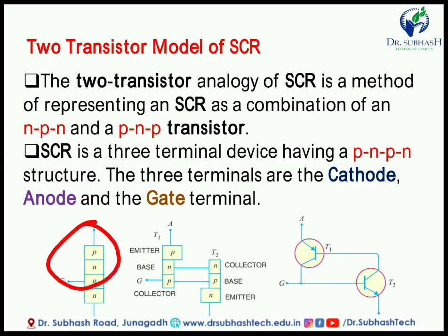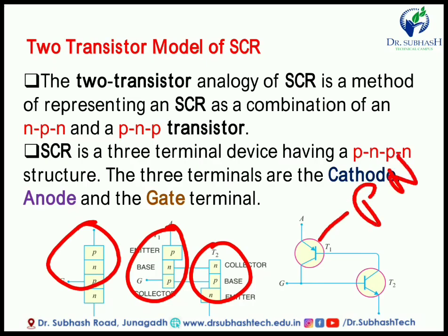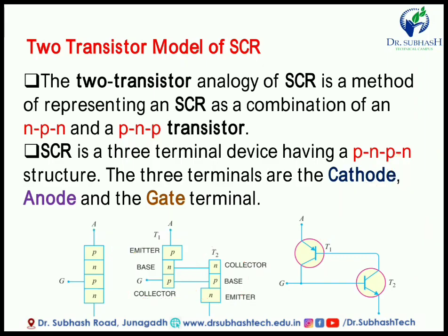Now in this tutorial we discuss T1 and T2, which means we use two transistors. T1 is a PNP transistor and T2 is an NPN transistor. There are a total of 2 transistors, and according to the conduction and blocking of these transistors, the current is different. In the symbol, T1 is a PNP transistor because the arrow is pointing inside the transistor.